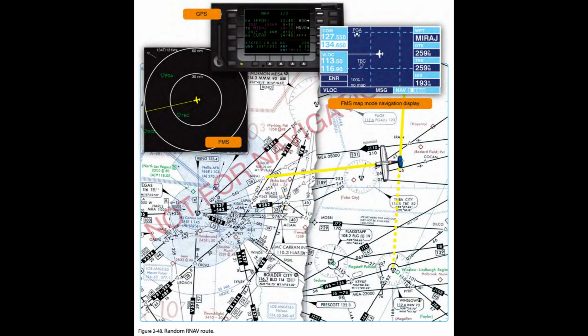During the flight deck review of the high and low altitude en route charts, the pilot determines that the best course of action is to fly direct to the MIRAGE waypoint, 28 DME northeast of the Las Vegas VORTAC on the 045-degree radial. This places the aircraft 193 nm out on a 259 degrees magnetic course inbound, and may help to avoid diverting north, allowing it to bypass the more distant originating and intermediate fixes feeding into Las Vegas. The pilot requests an RNAV random route clearance direct MIRAGE to expedite the flight.